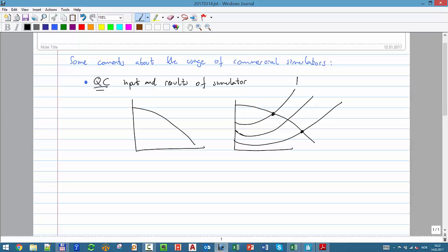So here, which one has higher wellhead pressure? That's bottom hole pressure versus Q. Which one of these has the highest wellhead pressure? 1 is higher than 2, which is higher than 3. Why? Just because when the back pressure is higher, I should be producing less rate.